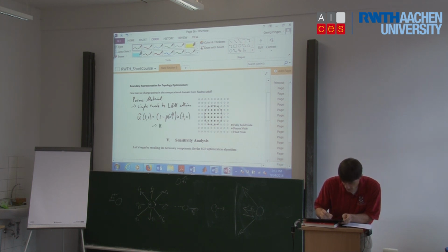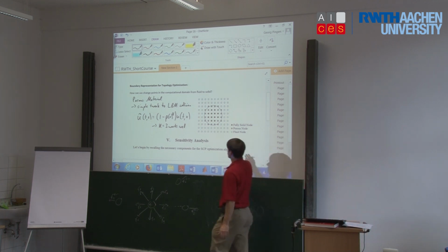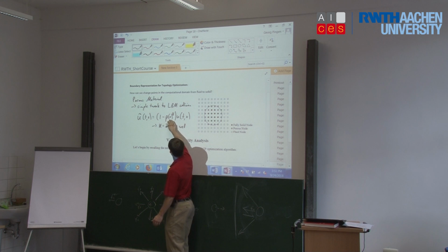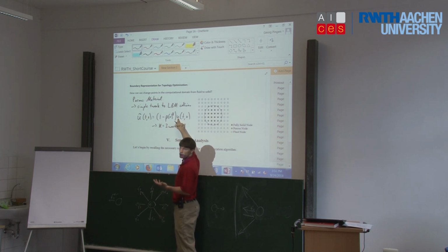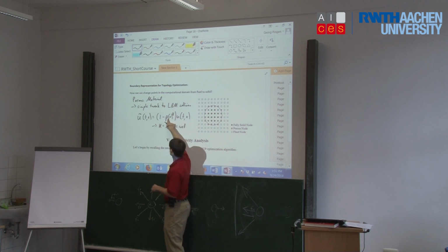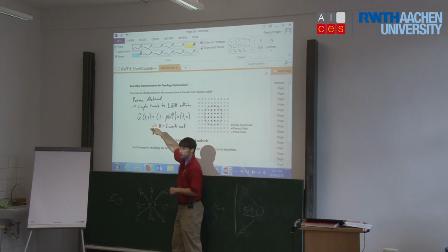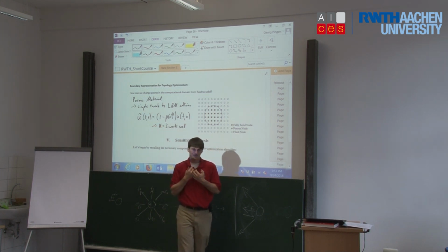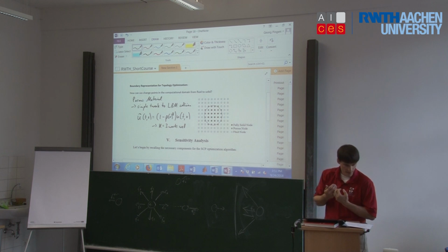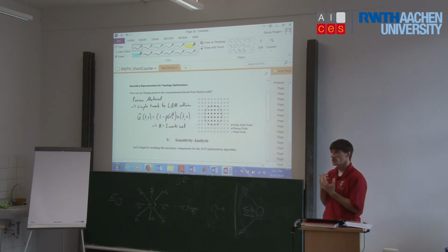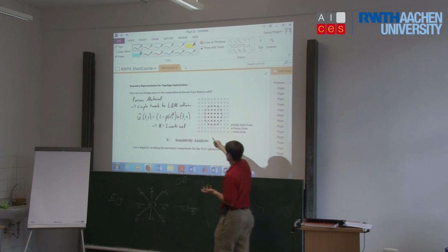Where kappa is equal to 3 works well. So if we have this value that goes to 1, when the porosity is 0, we just use the velocity calculated in the program. When the porosity is equal to 1, 1 minus 1, our velocity is set to 0. And so we're, in essence, dissipating all the energy with a porous material.